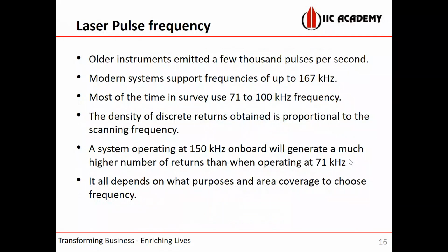Okay, I'll just go a little into how these pulses work, what the frequency is and so on. In the olden days, they used a few thousand pulses per second. Now they are using almost 167 kilohertz pulses, and modern systems are capable of recording this. As we all know, as the frequency increases, you get more accurate data and more information, but the only problem is that penetration will be less.